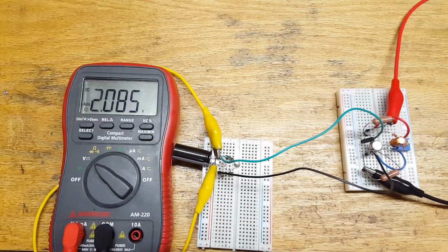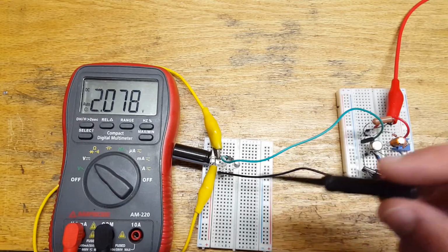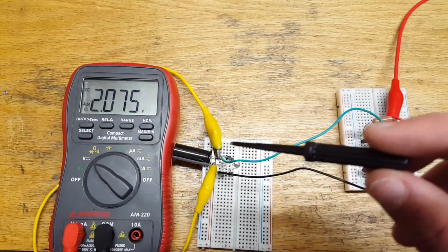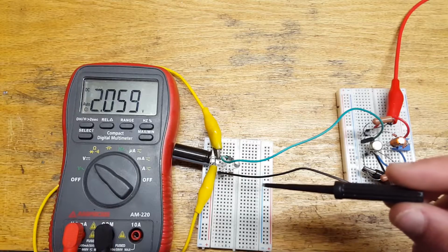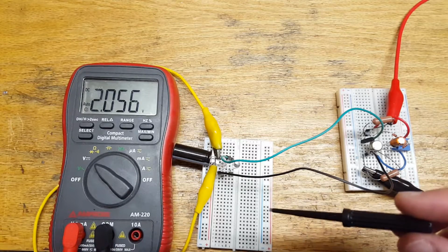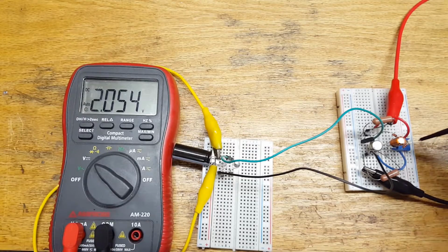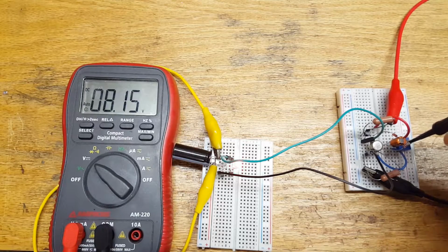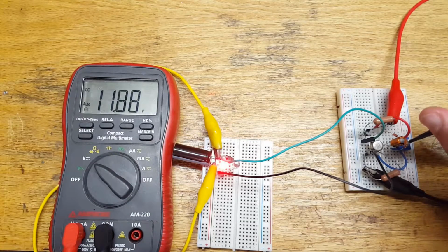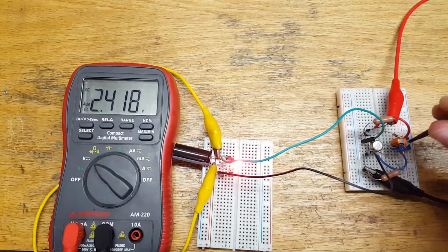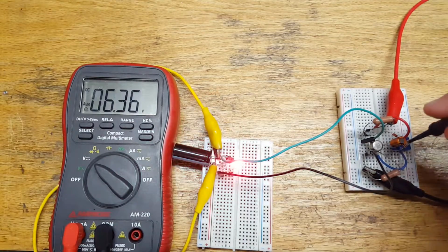Well, nothing beats a good old-fashioned demonstration. So I built up this little circuit here, which is going to apply a forced variable voltage across this capacitor, and I've got two little LEDs here which are going to indicate the direction of current flow. And the brightness of the LED will be kind of proportional to the current going through them. Anyway, watch what happens as I change the voltage on the capacitor. You'll notice that as I increase the voltage, one of the LEDs lights up. And notice as I decrease the voltage across the capacitor, the other LED lights up. Now if I change this really fast, you can see how bright I can make these LEDs.